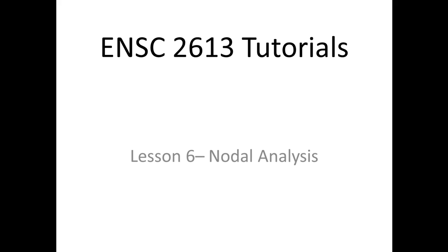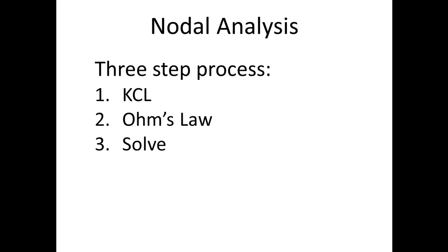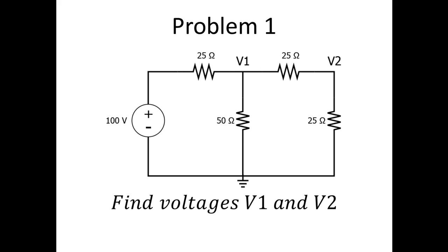Today's lesson will cover nodal analysis. Nodal analysis is a circuit analysis technique predominantly used to find the voltage of one or more nodes in the circuit. It is a three-step process, and the steps are KCL, Ohm's law, and then you solve. In this problem, we're asked to find voltages V1 and V2.